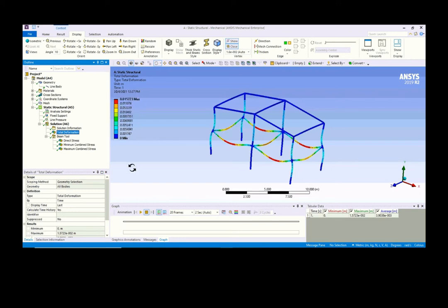You have to get to a point where the deformation between the meshes basically doesn't deviate or change too much. That is a tolerance, a percentage of change between the two mesh sizes that you use. Then you can use the final one, the one where before and after you refine there is not much difference, within a certain percentage that is acceptable. Then you use that particular mesh size.